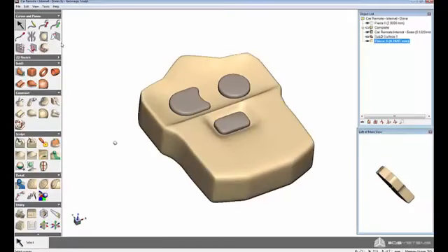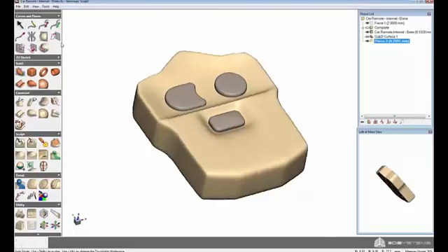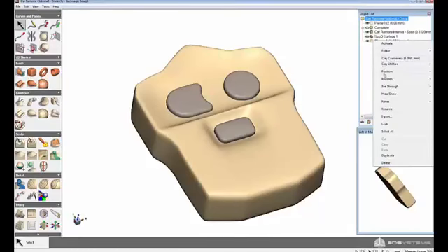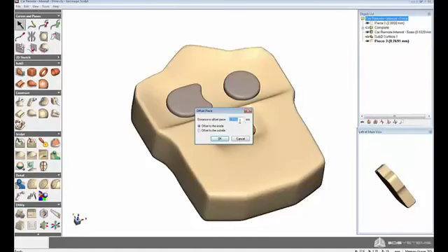Now we have a clay version of this. And what's nice about clay is this is where you can do things like adding grips, details, logos, and really flesh out the aesthetics of your design. Right? So first thing first is we know that, of course, we're going to need to have this be hollowed out, right? Some type of shell. We can't just give them a solid body. We're going to shell it a little bit. So we'll go ahead and do that first, or at least do the first steps of that. And the way we're going to do that is creating an offset piece on the inside. Right? So maybe this thing will be, we'll say, a millimeter.